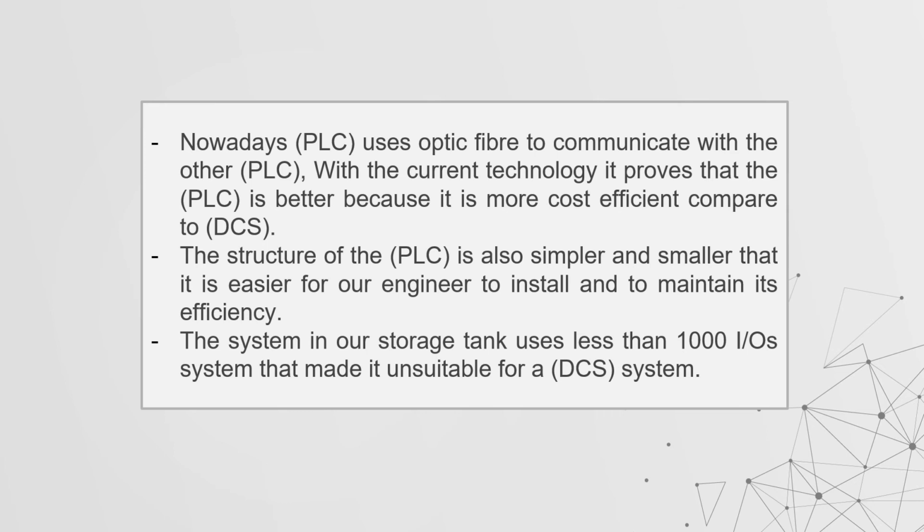The system in our storage tank uses less than 1,000 input-outputs, which makes it unsuitable for a DCS system. So that is why PLC is better for our storage tanks.